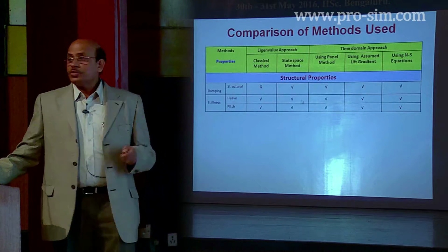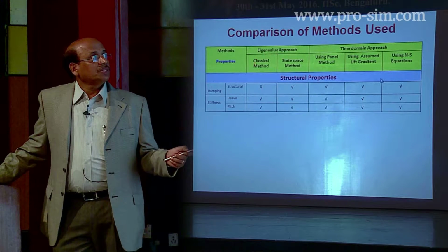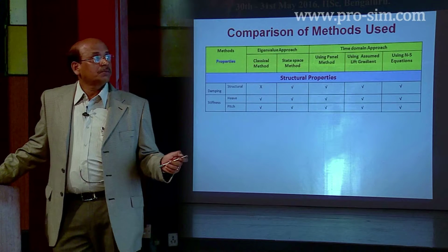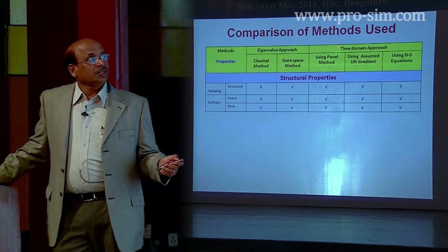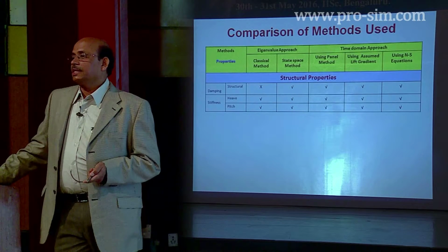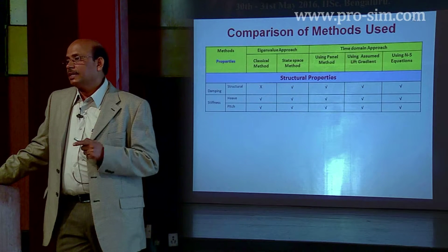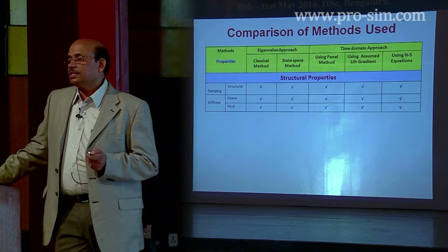Now, coming to the solution approaches, we have what are known as the eigenvalue approaches, which are used in the classical methods as well as the state space methods. And coming to the time domain approaches, we use Newmark's techniques, we use finite difference techniques, and all these high fidelity techniques of solving the equations.